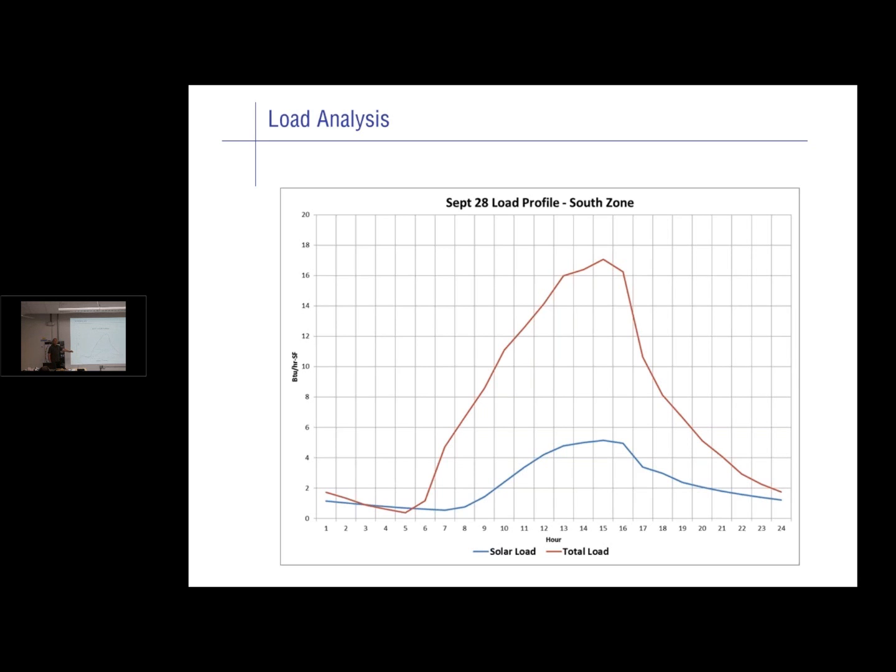Kind of weird when you run solar loads in eQUEST. Why do we have a solar load when the sun's not out? DOE-2 and eQUEST out of the box is going to model a thermal lag associated with the mass of the construction components that are in your model. So this 3 a.m. solar load is a carryover with the math that's built into DOE-2. It's a thermal lag. It's a carryover from the previous evening and afternoon. Some of that solar load got embedded in the masses and is being pulled back out of the mass by the calculations several hours later.